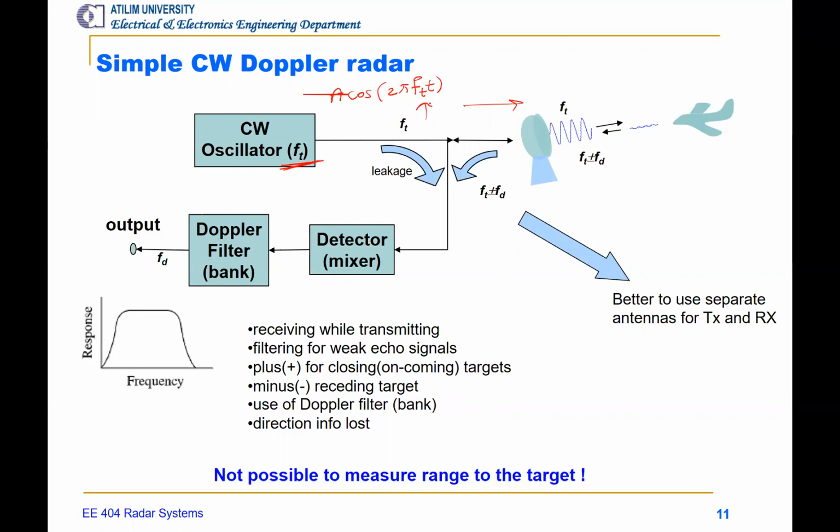So I know the transmitting signal frequency, and if there is a motion in the target, then we expect Doppler shift. And then the received signal frequency will be simply shifted by fD. So we can write that just like, for example, K times A. This K is a constant showing the attenuation or other effects in the channel. Cosine 2 pi (f plus or minus fD) t.